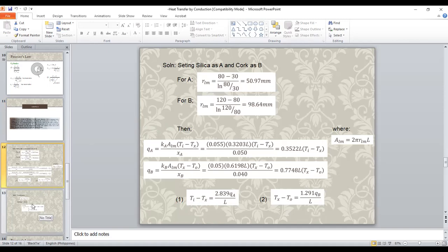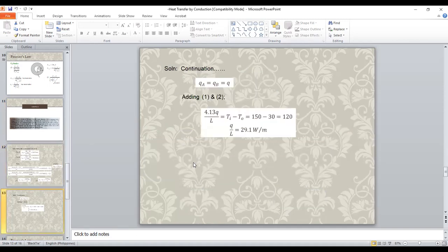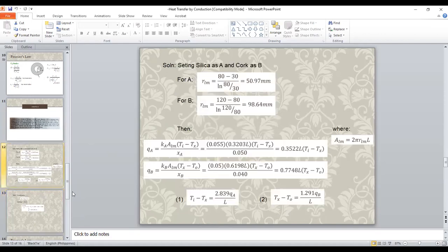Anyway, so that we will not lose any time. So you add the two. If you add these two, i-add mo ining duha, right? Now, why i-add mo sila nga duha? Kay isa si QA, isa si QB. Isn't it that Q sub A is equal to Q sub B? So literally, you can add the two. You can simply change the QA and the QB to Q because anyhow, it's just the same for whichever material we're talking about, the pipe, the foam, and the cork.